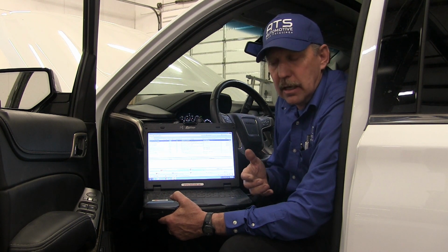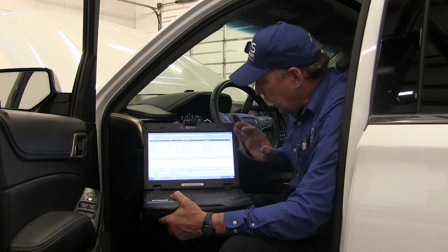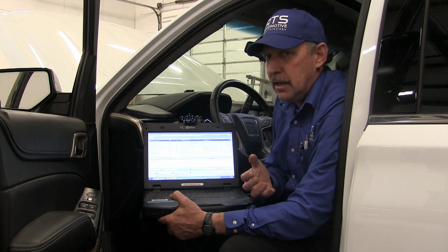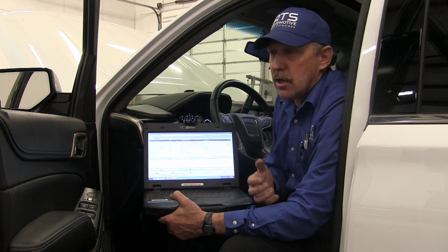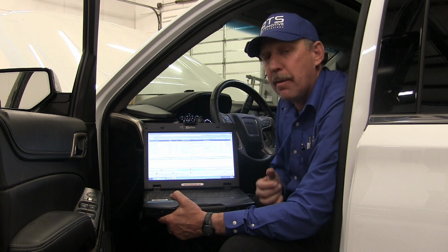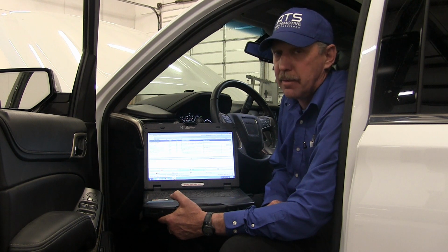So once again, this starts to make me think, by the way the scan tool is presenting the data, that this problem is intermittent. And it's not currently on the car. So we have to think about that, because when we're looking at a car, it has to have the problem presently for us to find the problem, okay?